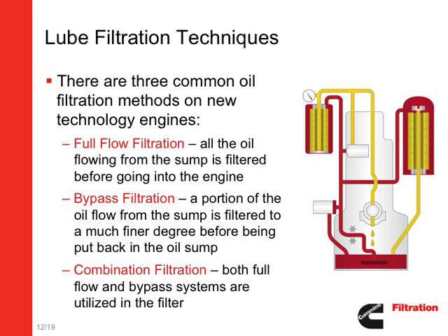There are many aftermarket bypass systems, but most require mounting a separate filtration device on the engine and routing plumbing from the engine to the bypass filter and back to the engine. New technology combines both full flow and bypass filtration in one filter unit. The filter is fully self-contained with no extra plumbing required, which means no opportunities for hose issues or fitting leaks. In addition, this technology does not rob oil flow from the engine and divert it to the engine sump.